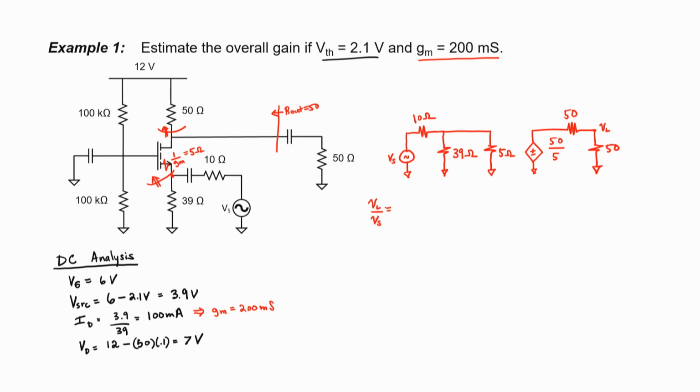So we're going to have 3 components here. We have an input voltage divider. So the voltage divider set up between the 10 ohm resistor and these 2 resistors in parallel shows a particular characteristic of the common gate configuration, and that is that the input impedance tends to be really small. From the perspective of our input signal, the input impedance lies to the left of this line. In my equivalent circuit, it lies to the right of this line.